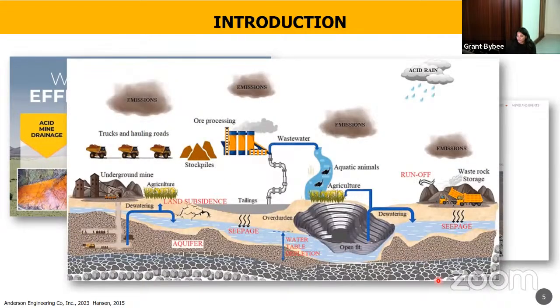What we had is open pits which were being dewatered, but are now filling in from various sources. The problem is we didn't know where these sources were. There are so many different possible sources, so now we're trying to say, what is the actual source? Where is it coming from? Is it seepage? Is it infiltration into our aquifer?